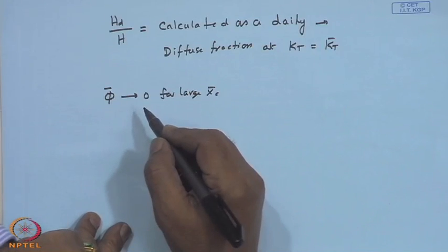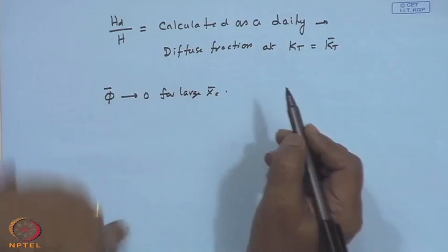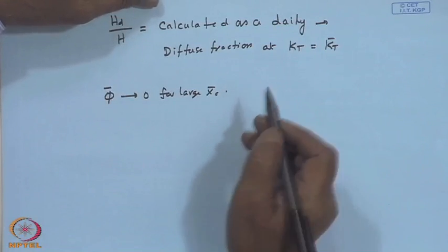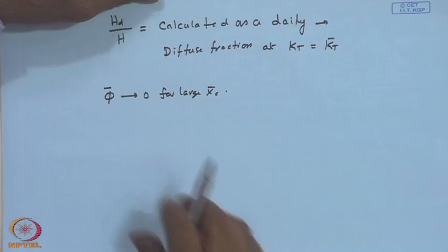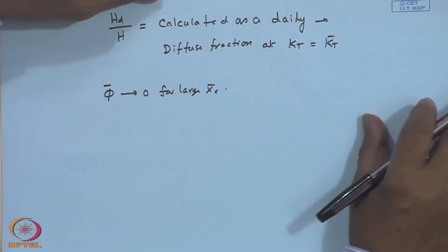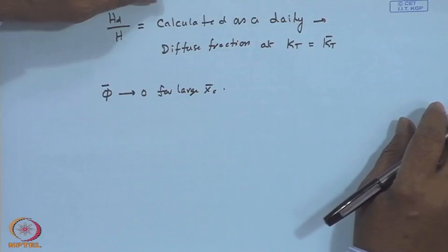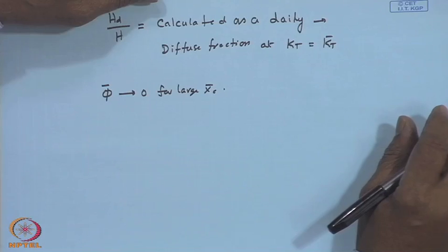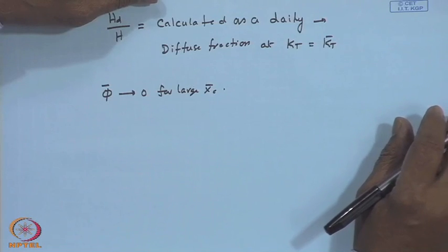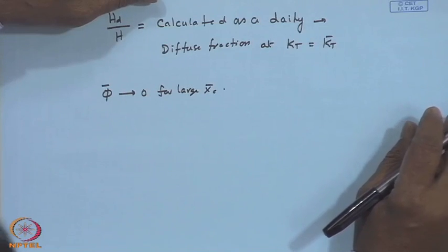So, there are certain limitations. First of all, concentrating collectors need a satisfactory utilizability method, then non-south facing surfaces need to be treated, and whether R n by R bar adequately represents phi beta delta needs to be examined.